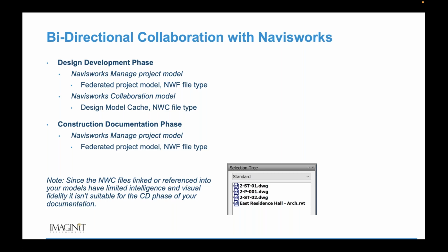I mentioned the fact that there's some new capabilities or functionalities that have come from Navisworks for us, and this is more toward bringing the model information from those Navisworks models or the Navisworks cache files that we've created that represent models in different file formats than the design tool that you're working in. So I can link or reference a Navisworks cache file, the NWC files, into any of my Autodesk design software.